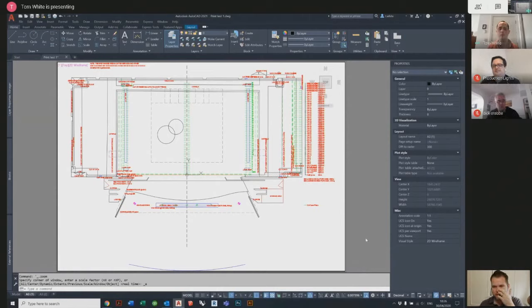Is that right? Is that absolutely it? So at the moment, it operates exactly the same as it would if you were in model space. It just happens to be this view in from paper space. Which is why I choose to print from the paper space, because it means I can replicate the same drawing multiple times. For example, I've done those 2 circles, but it could be a stage floor or something I could add in.